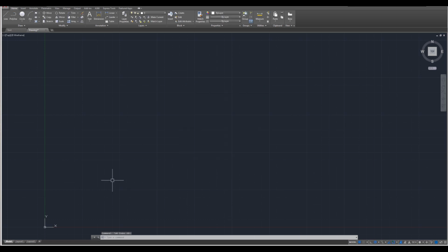I'm going to list out 8 different coordinates, and these are all going to be absolute coordinates. So I'm going to type in line, enter, and to specify an absolute coordinate, you have to use hashtag first. So I type in hashtag, and then the first coordinate is going to be 1.5, comma, 4, enter. And you'll notice right away that it is 1.5 units away in the X and 4 in the Y. So that is an absolute coordinate.